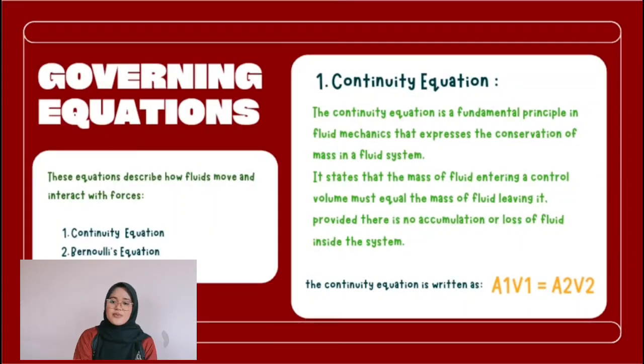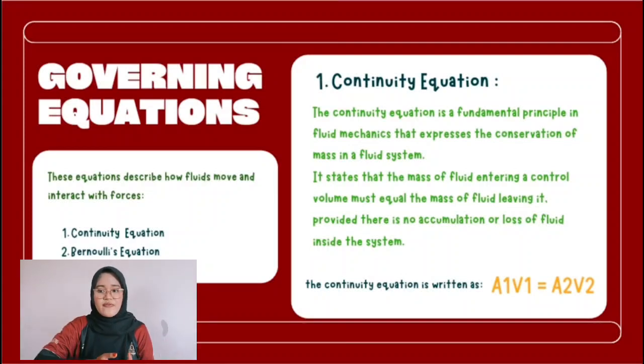Next, I will explain about governing equations. These equations describe how fluids move and interact with force. We have two governing equations, which are the continuity equation and Bernoulli's equation. First, what is the continuity equation? The continuity equation is a fundamental principle in fluid mechanics that expresses the conservation of mass in a fluid system. It states that the mass of fluid entering a control volume must equal the mass of fluid leaving it, provided there is no accumulation or loss of fluid inside the system.